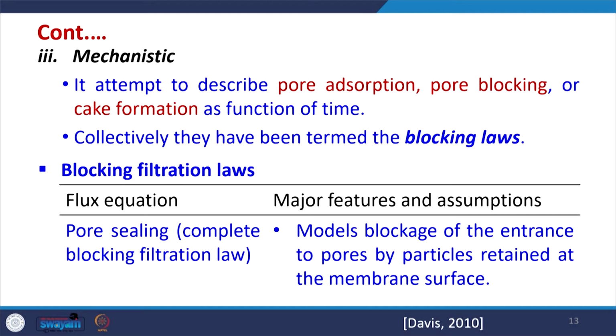So, we try to see how we can model the pore adsorption, because this is one of the mechanisms, then pore blocking and cake formation as a function of time, and collectively they are termed as blocking filtration laws. So, this is called blocking laws or blocking filtration laws, and these are the different flux equations and major features and assumptions which are there.